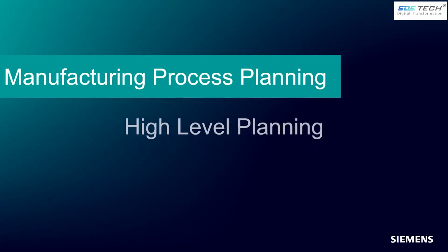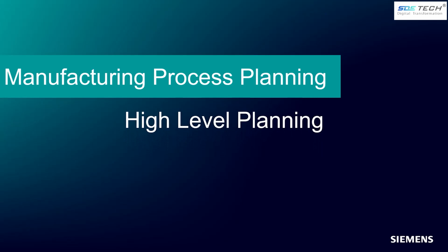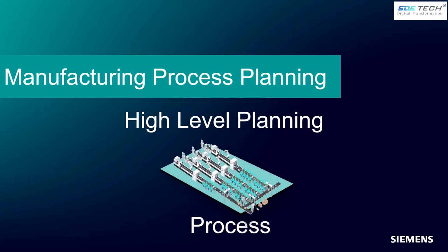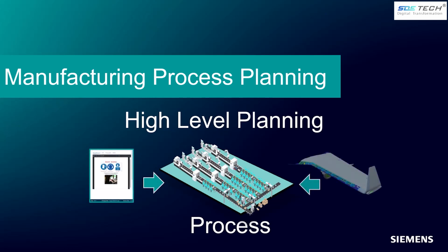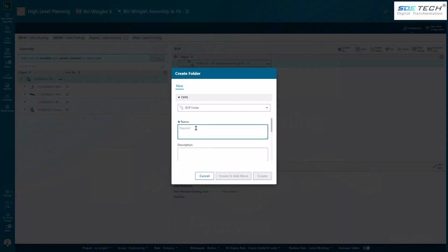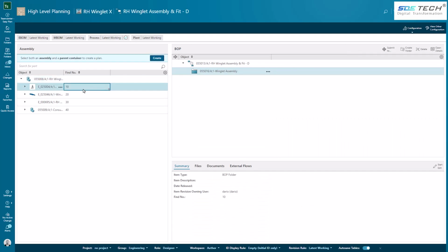Once the manufacturing bill of material is created, the bill of process, which provides the process steps, can further be enriched with work instructions, part association from the MBOM, and further detail to the sequence of operations. Firstly, I'd like to create a winglet assembly process of which to associate a group of material components that will be assembled together.